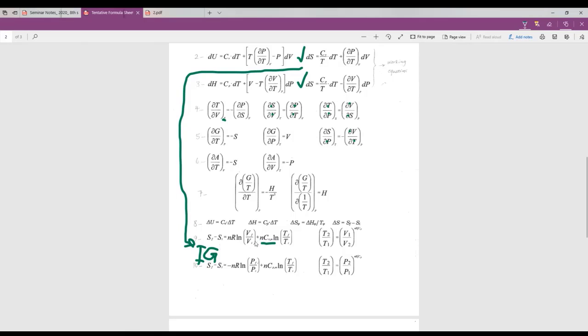And for this equation, for the case when CV of the system is constant. For this case, CP of the system must be constant. Okay, so it is important: CP is constant, CV is constant, and ideal gas. But we haven't specified anything else for these two equations, which means that you can still use them for both reversible and irreversible processes.